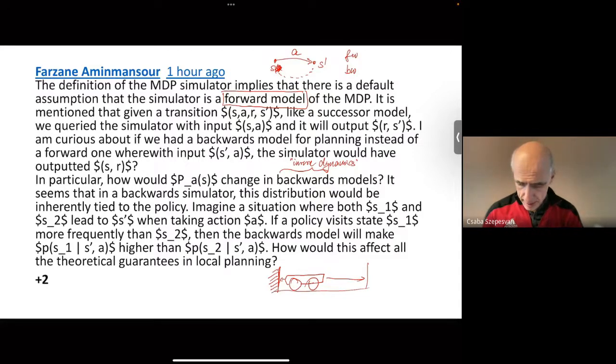But maybe the last step that it took, the action was to go left, but we were too close. We are measuring 0.1 seconds later, and we bumped into the wall and just stopped there. But we could have been here, or in any of these places, right? If we're close enough to the wall, then the wall is going to stop us in the next 0.1 second. And there is no unique way of telling which position we came from.